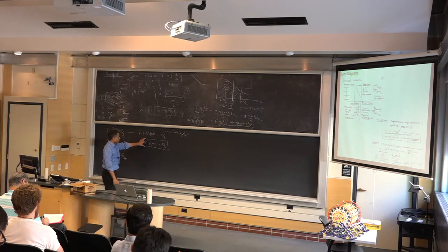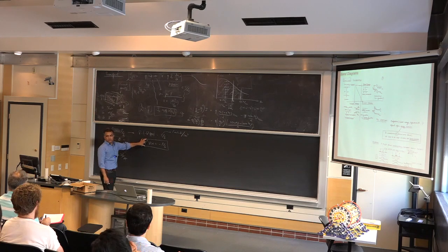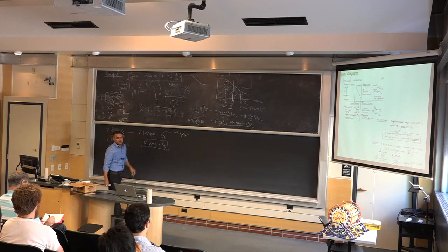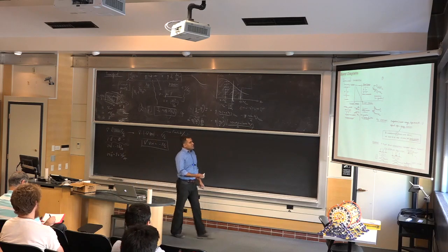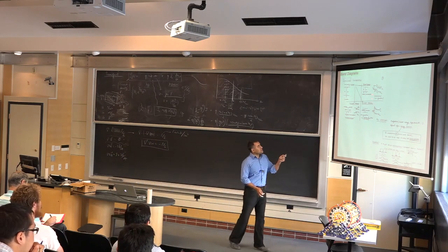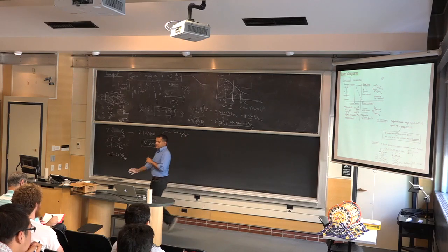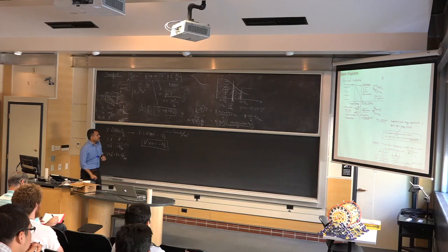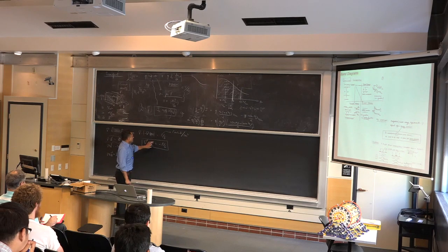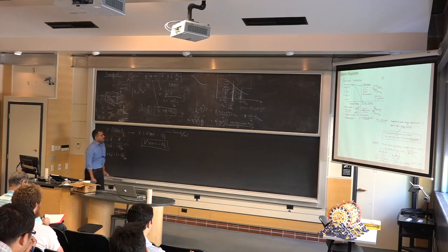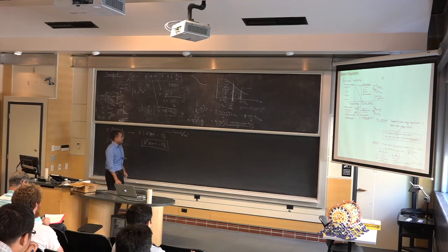Let me just conclude by saying that the energy band diagram is a pictorial representation of the Poisson equation. That's all there is to it. We're drawing a picture of that in space. And it just so happens it's the pictorial representation in a semiconductor, which has band gaps, so band edges are changing, and that sort of thing. So that's what we're going to solve. And I think you know the solutions to many problems already as far as solving the Poisson equation.